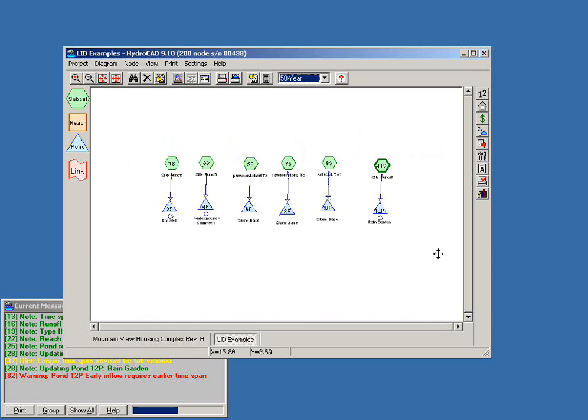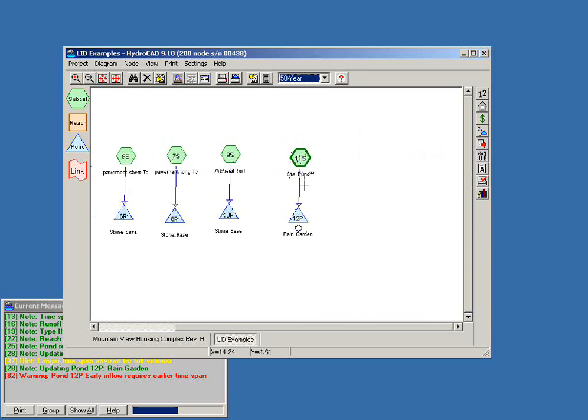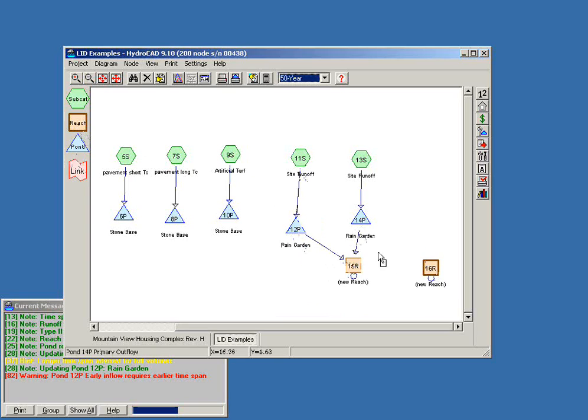So if we set up an initial subcatchment and pond, we could then do a controlled drag in order to create a second subcatchment. We could do the same for the pond. So now we have a second system, and then we could interconnect those two. So we might have another piping system that this water is flowing through, and we could take the overflows from each of these structures and run it into that pipe system. So various approaches depending on how your specific model is set up.